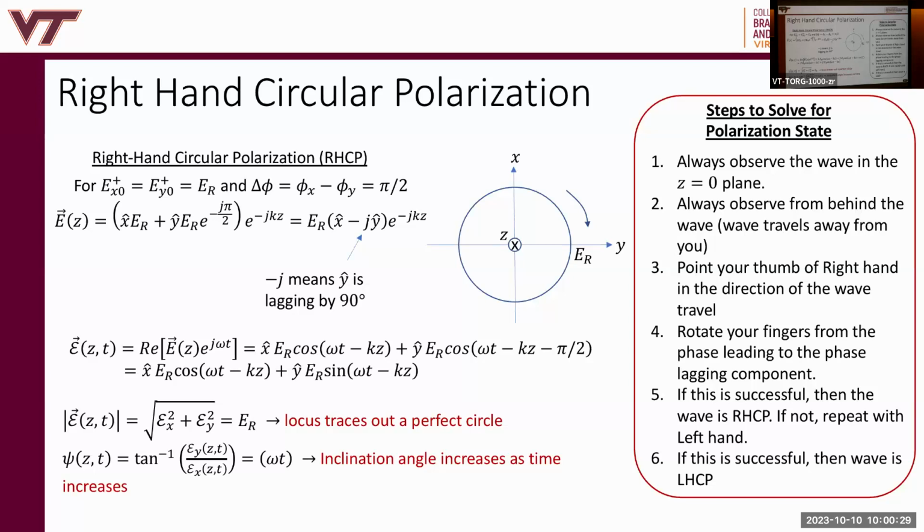Yeah. You can do that. The problem is you have to have very controlled orientations of your antennas, because you're putting information on the different polarization components. You want to make sure that when you send X, it gets received as X. So you should probably have a fixed transmitter and receiver. But yes, you can do that. And hopefully your channel is not anisotropic or doesn't do anything to the polarization.